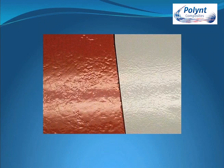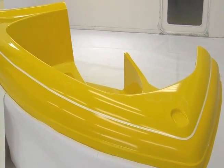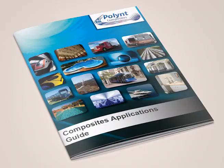If the defect is fibre print, surface distortion or weathering, sanding and buffing is the best remedy. We will demonstrate spot and spray patching in this video. The patching section of the applications guide describes the other types of repair.